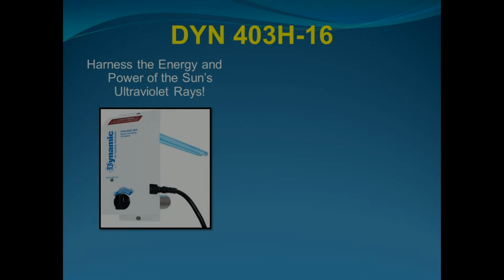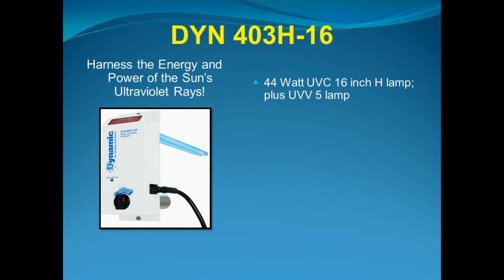Right. So let's just go through the features here of the ozone generating product, the UVV system that we have. It has the UV light, so it still has the germicidal kill that you need. And then the smaller lamp on there is encapsulated in 2 cylinders. We have a knob on it, and we can turn it up or down for different sizes of homes. So now we can adjust the level without having to have 15 different units for 15 different size homes. That makes sense. So we've got the UVC energy, but what that smaller unit is doing is not any germ control. It's the oxidizing system.